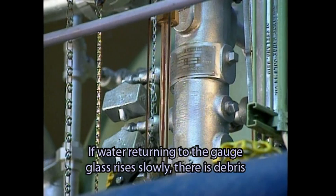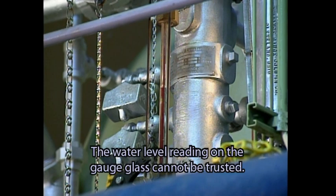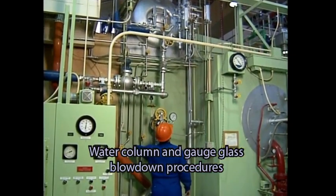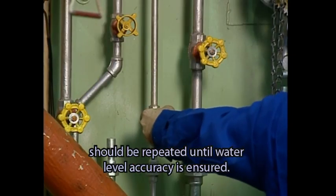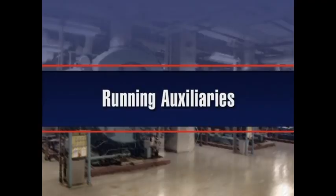If water returning to the gauge glass rises slowly, there is debris or mud in the piping. The water level reading on the gauge glass cannot be trusted. Water column and gauge glass blowdown procedures should be repeated until water level accuracy is ensured.